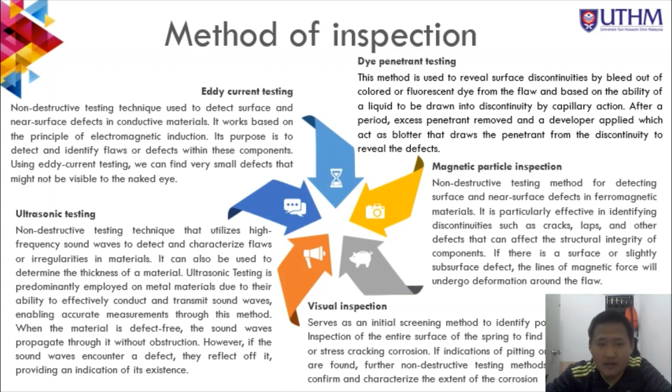Then there is eddy current testing. It is a non-destructive testing method which is used to detect surface and near-surface defects in conductive materials. It works based on the principle of electromagnetic induction. Its purpose is to detect and identify flaws or defects within a component. Using eddy current testing, we can find very small defects that might not be visible to the naked eye.